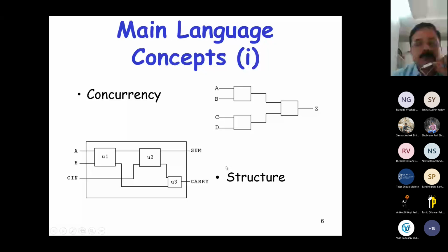When HDL was first developed, most logic simulators operated on netlists. The netlist is nothing but the list of gates and how they are connected. It gives the information about the list of gates and how they are connected, and is a natural representation of a digital logic circuit. It's not a very convenient way to express design, simulate, and debug.